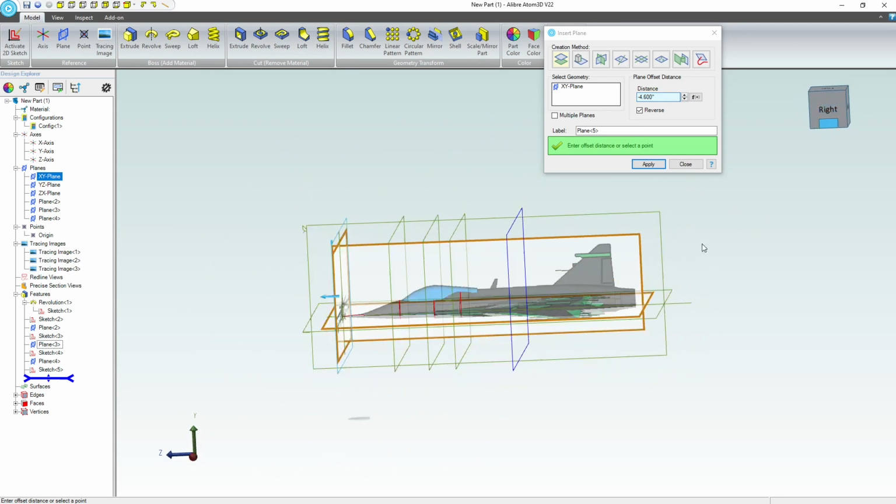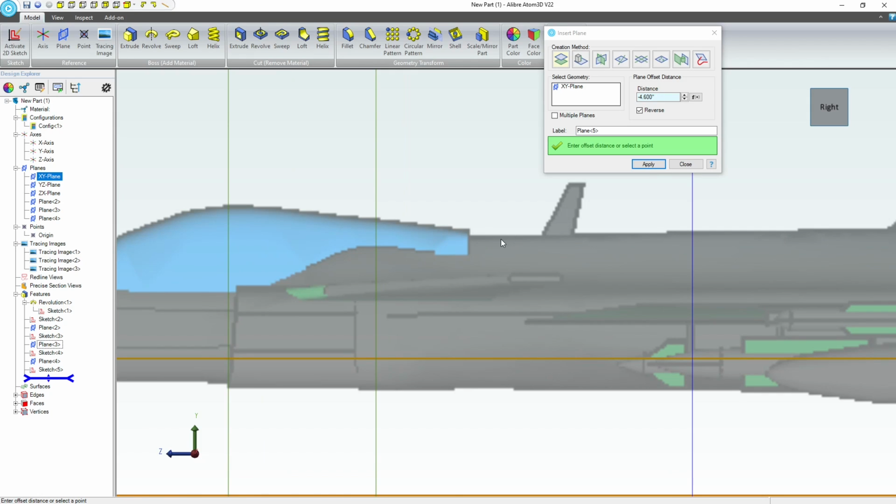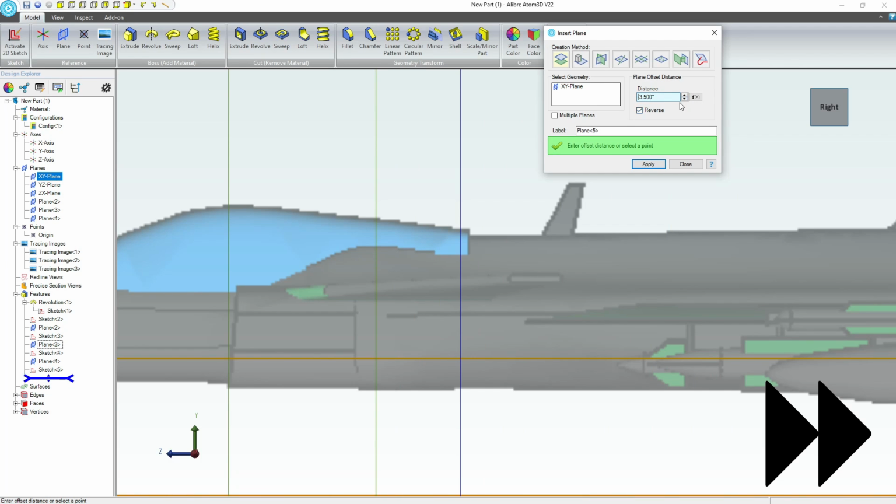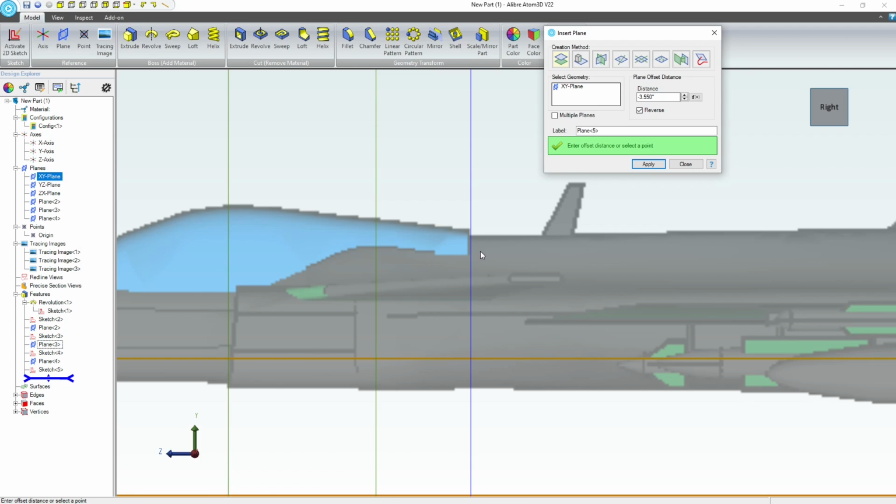We'll choose our right view, and we want perhaps this sort of minimum, not minimum, but maybe perhaps local minimum part of the body that we're lofting. I'm going to say 3.55 and then negative. There we are. That's not too bad. Yeah, I think I'm going to go with that. And I think I'm going to have the body come up here to this point, and then our cockpit or our canopy is going to show this kind of natural reduction.